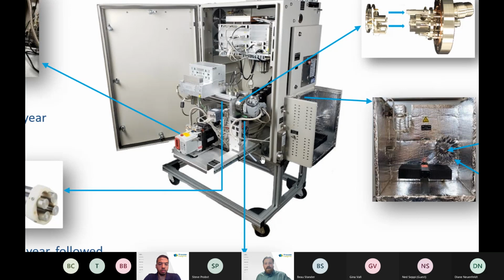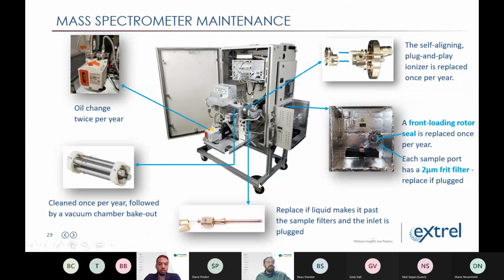There's a good and bad to that. The bad thing is you're no longer getting your gas in to analyze, but the good thing is that plug protects the internals of the system from anything that was in that liquid. So greases, hydrocarbons, or acids, like one of those HF sites. That's all taken by the inlet, not by the mass spec itself.